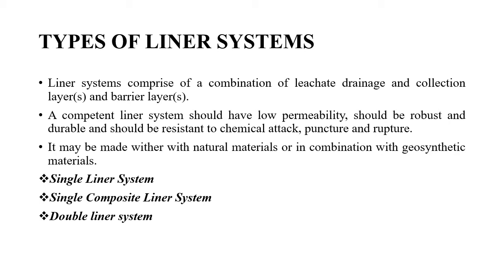Okay, so whichever material we choose, it has to be very durable, and it should be resistant to all types of puncture and rupture, and most importantly it should have very low permeability or hydraulic conductivity, so that it can prevent the migration of any such polluted solutions, or what we call leachates.